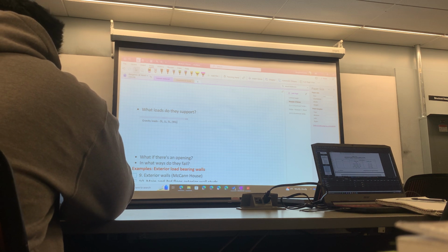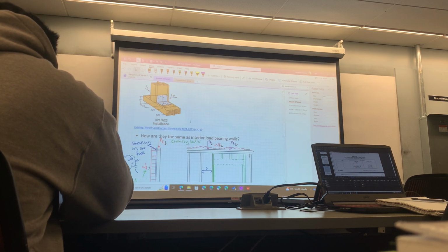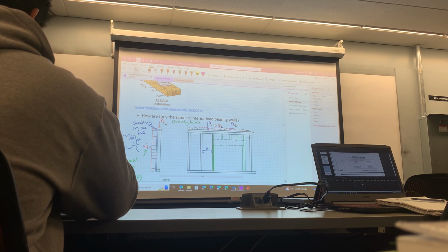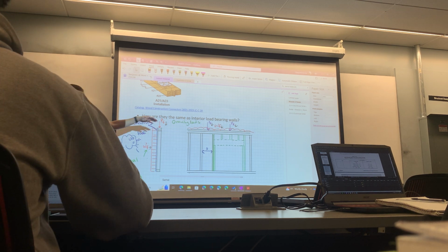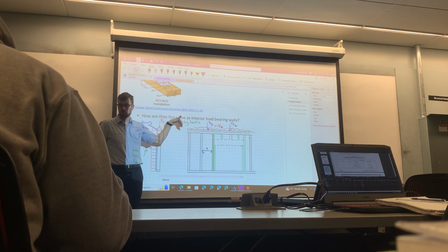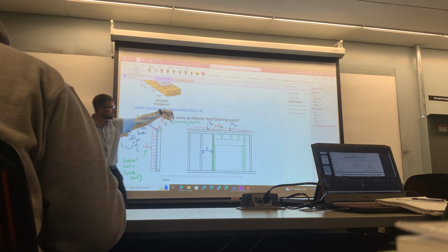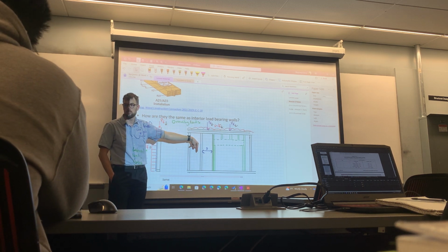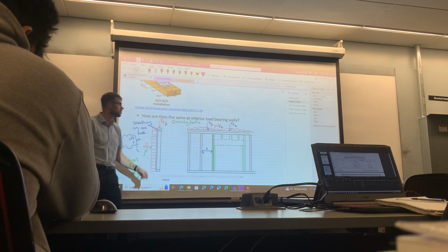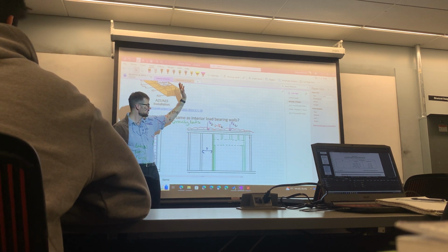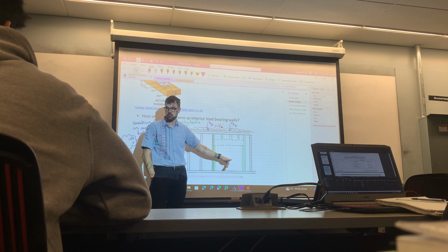Escarpment. You guys are doing wind and steel, right? Yep. So what happens on the roof with a wind load? It causes uplift, and there's also downward pressure. There's a balance between upwards and downwards pressure depending on which face you're on. That will cause loads in the downward direction. So even though it's not gravity causing those loads, they're still going to add to here. These loads from above could include some uplift and some downward forces from the roof due to wind.